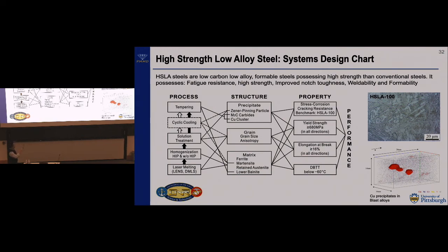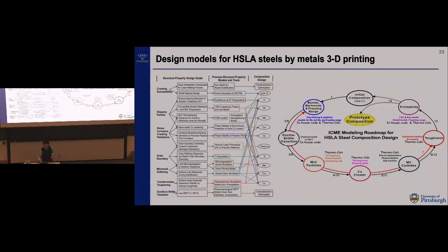And here is a grain. You don't want the grain size to be large, okay? We're probably talking about prior austenite grain size once you solidify from the austenite phase to martensite and bainite, which is a kind of term we're using when discussing steel structure. And then we want to control the initial microstructure, okay, where you're starting from solidification, the later melting process. But you do have the chance to restructure the microstructure during the post-heat treatment. So in additive manufacturing, alloy design is always combined together with post-heat treatment. So this is one of the things that we have to make sure of.